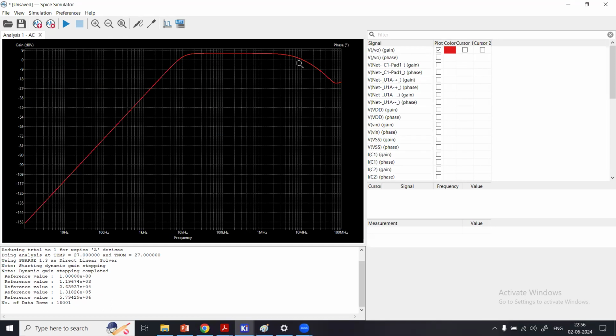So here at very high frequency of more than like 8 megahertz, my gain drops again. So if I want to take care of it and see if I can do something about that, because I would want constant gain for all the frequencies right here. That's the ideal behavior of a high pass filter.